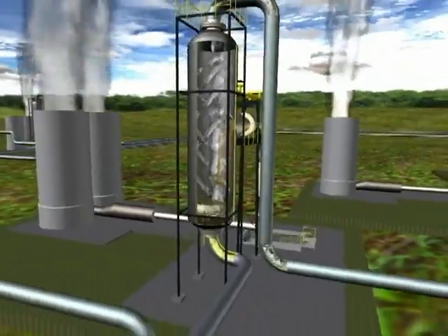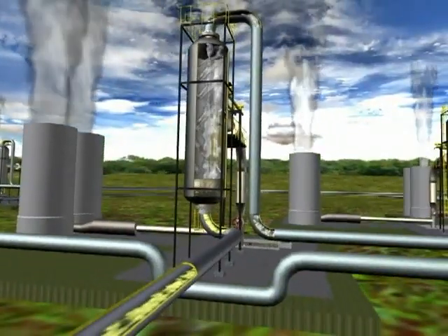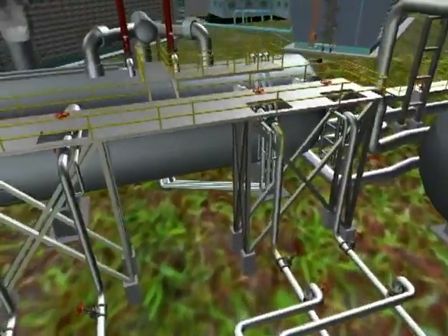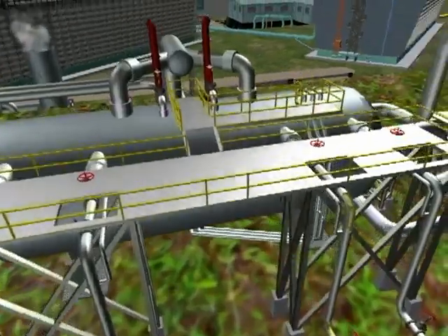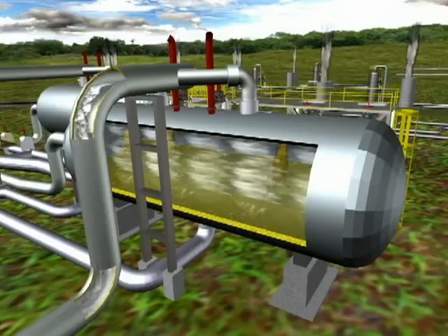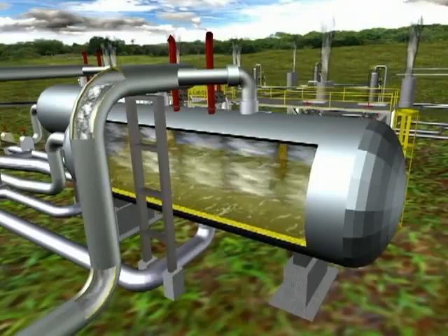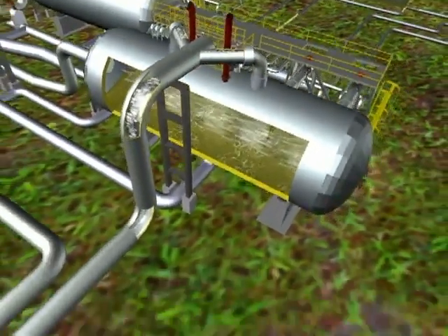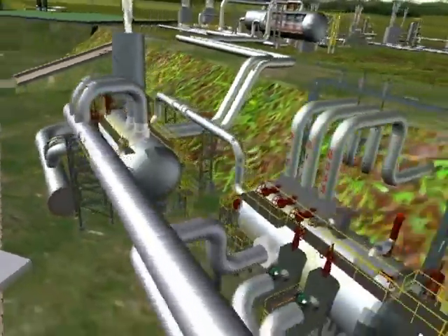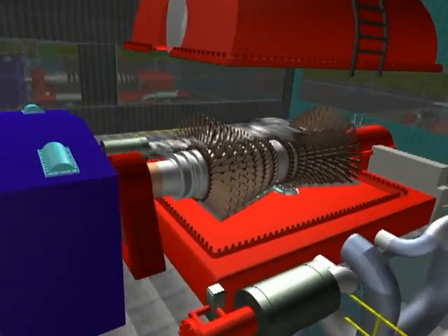Going back to the cyclone separator, the geothermal water separated from the steam is brought to a flashing system or flasher. The function of this system is to separate another steam portion from the hot residual water before it goes to the reinjection system. This second separation steam is known as low-pressure steam. It is transported again to a collector and later conducted to the turbine, where both steam pressures turn the blades of the turbine to generate electricity.